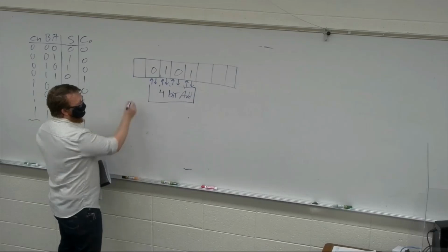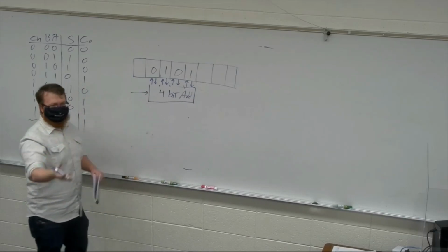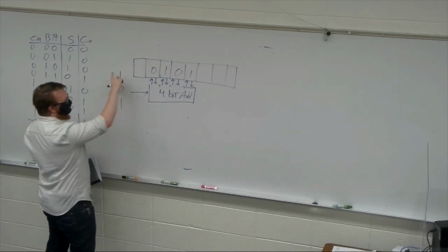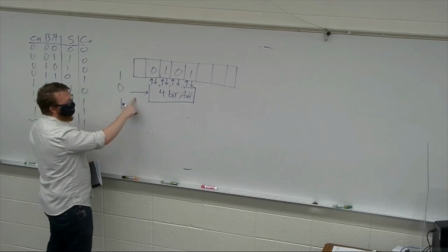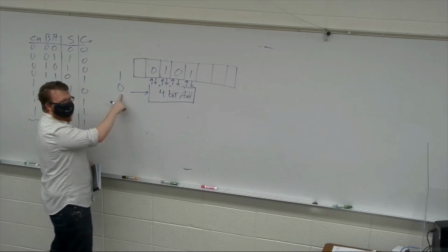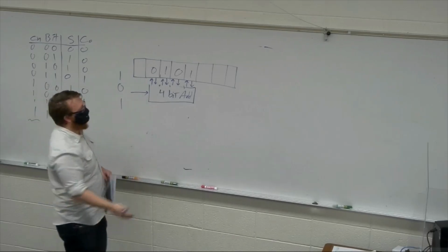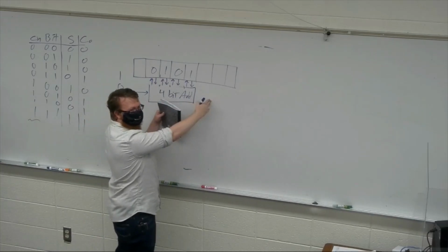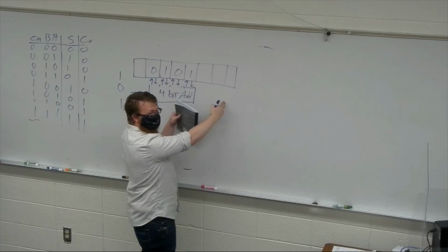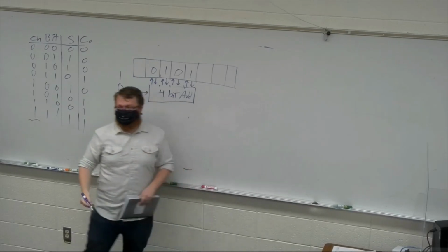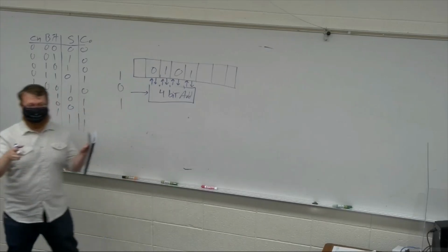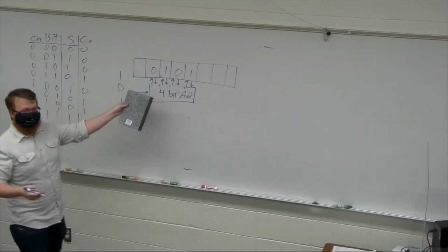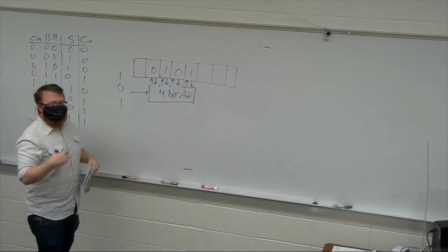What it's going to do is take an input that is just the multiplier, right? And it's just going to shift through those. And if there's a 1 here, then it can add the multiplicand back into this, and then just shift 1 over. And if it's a 0, just shift. There's a 1, add, and then shift. So that's all it's ever doing, is adding or not, and then shifting, and then adding or not, and then shifting.